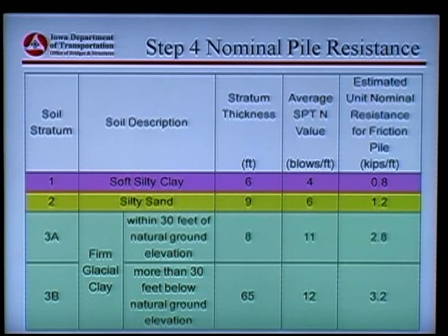The next point down was where we get down to this 30-foot depth. So now we're going to have the 15 plus the 8 right here. So now that pushes us down to 23-foot depth below the bottom of footer. We're going to carry down the 15.6 that we summed from before, and we're going to add to it 2.8 right here times the 8-foot thickness. And that's going to give us 22.4. So 15.6 from before plus the 22.4 gives us 38 kips.